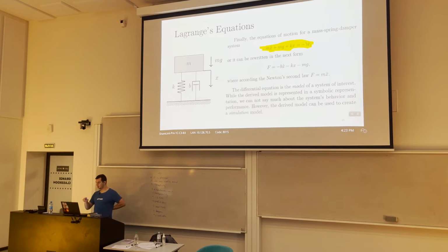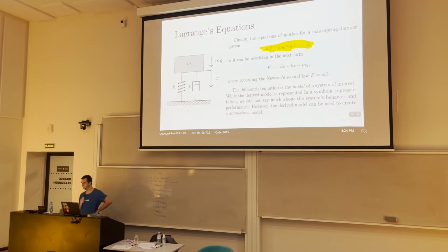Here x is not actually position; it's deflection, so zero here is not the rest position. Second of all, the damper will dissipate the force of inertia of this system. But actually, we can say that the behavior of the system depends only on the initial state of the system. The trajectory or the path of the mass will be, for example, a dissipating sine wave. But we don't know yet because we don't know the initial state.